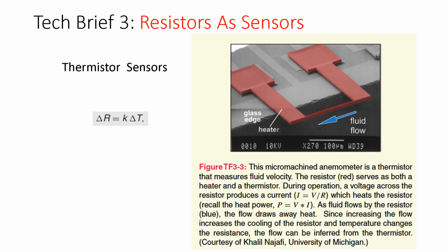That water is going to pull away some of the heat from that very, very thin resistor there. And as we saw previously, resistance changes in regards to temperature. And so what's going to happen is, the more heat that is pulled away, or the faster the fluid is moving to pull heat away, we're going to get a very different change in resistance. Essentially, you're going to be able to suck more of that heat out of the system, and that's going to be able to be measured.